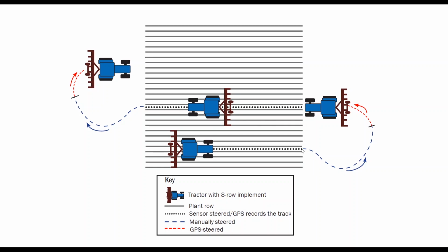When you disengage the auto steer here, it records a point a short distance back from where you disengage, plus a point further back to create an AB line. It takes that AB line and calculates a distance X perpendicular to that AB line for the next pass. While you steer disengaged around to the next pass, when you get to the halfway point between your original pass and your next pass, this system will automatically change to a GPS steering mode. When it changes to GPS steering, you can engage the auto steer and it'll GPS steer into the next row.